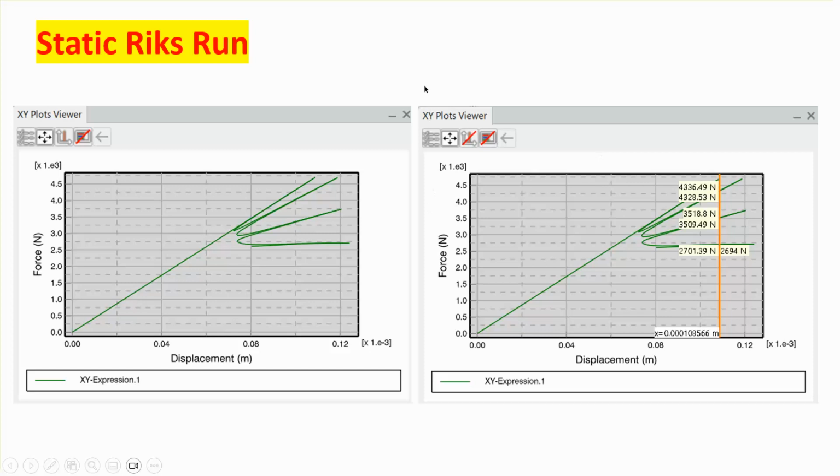Now, because these things take time, all I'll do is show you the steps for the static case, which obviously is not matching his result closely. There is no dip shown, but if you want to do the dynamic or the Riks step, then all you have to do, instead of selecting the static step as procedure, is select implicit dynamics, or the static Riks step.